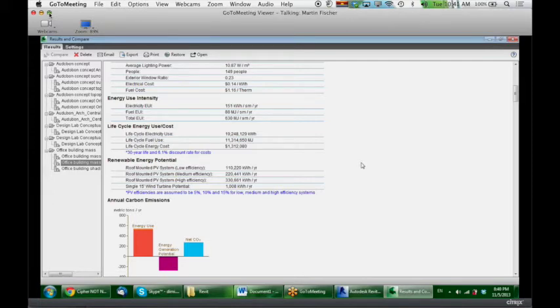Yep, that's correct. And then we can start looking at our performance factors. A very handy and useful number we can look at is the energy use intensity. Revit comes up with 3 numbers for the EUI: electricity, fuel, and total. The main reason why that's useful is that it's a very good energy metric as it's a per area one, which means, as you see, it's per square meter, which is very helpful when we want to compare projects of different sizes or different square footage.